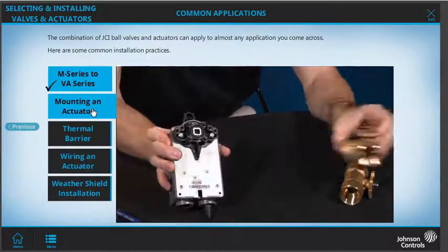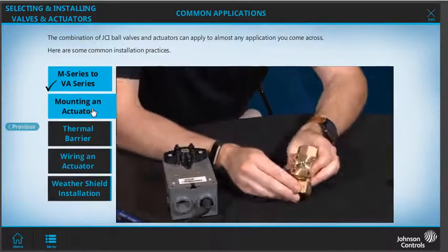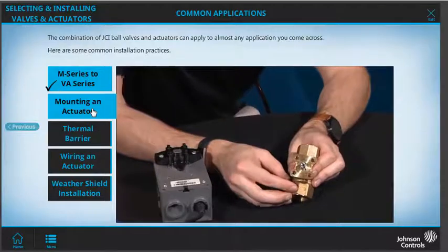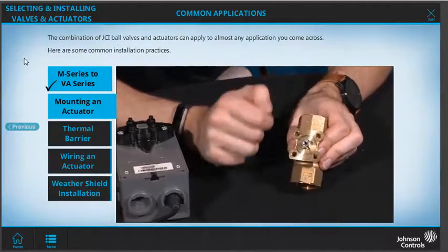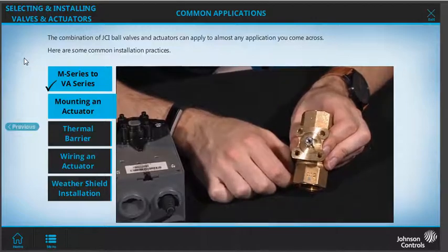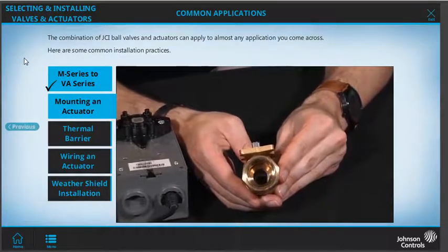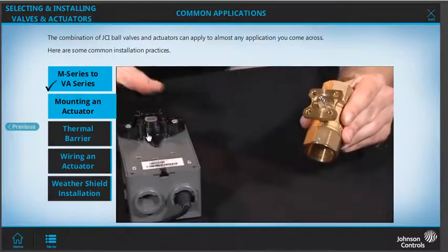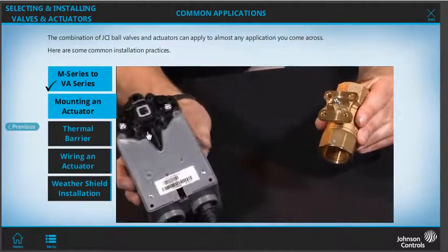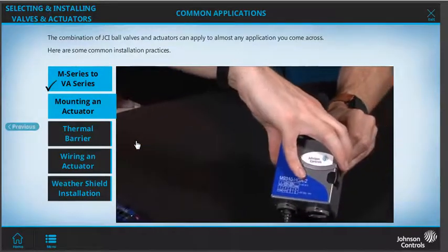Next, we'll demonstrate the installation of the actuator onto a 2-way VG1000 ball valve. This is done the same way as the 3-way valve, with only the indexing marks on the valve stem being different. They are a straight line, mirroring the straight hole that is through the ball in the valve. This valve is full open, so we'll want to orient the actuator with the anti-rotation slot towards the B port on the VG1000 ball valve.